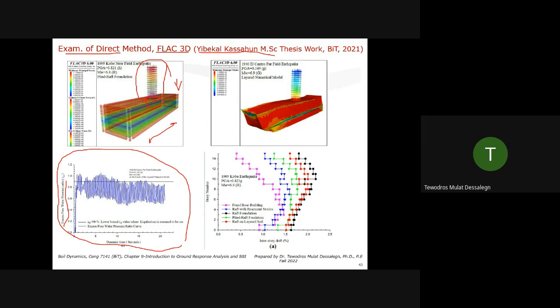Or you can use software to do this. The pore water pressure gets to around 1 and goes down. Liquefaction happened right away. There may be some limitation in the simulation. Usually it grows slowly and reaches 1. But he was able to get something. He also got forces, drift, shear forces, and bending moments in the structure and in the foundation elements. So you can look at the thesis he did and what he accomplished.